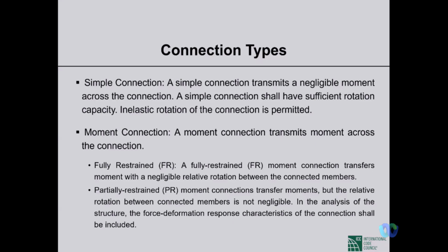So simple connection, though the term is simple, the calculation may seem simple, but there is a big important thing that we shouldn't overlook: in simple connections, the connections do not transfer moment from one member to another, that is, from beam to column or column to beam. It transfers only the shear force.